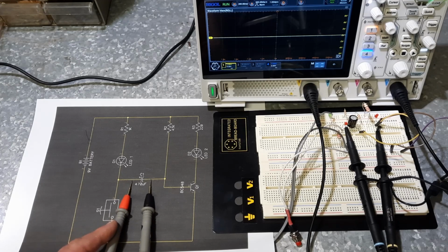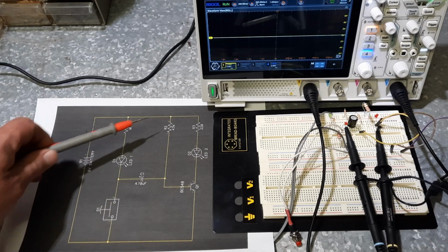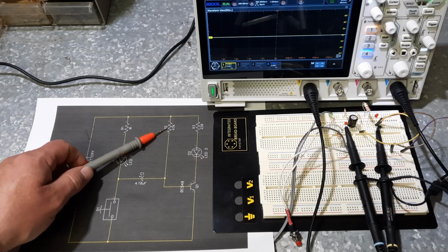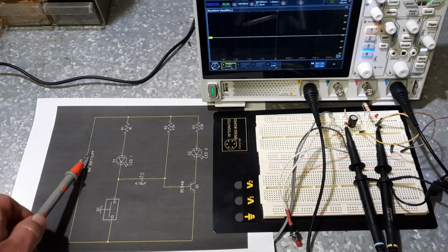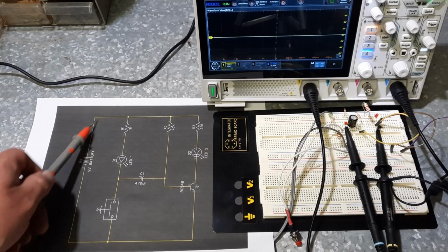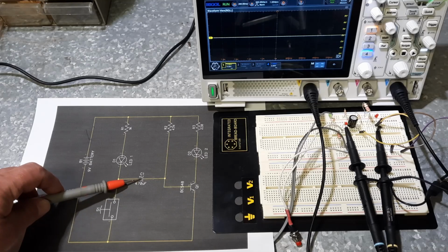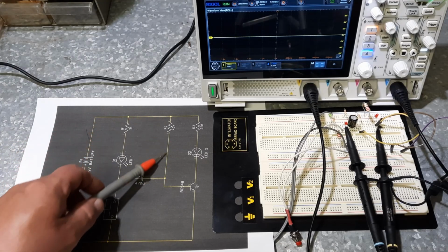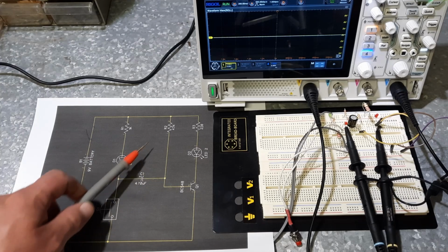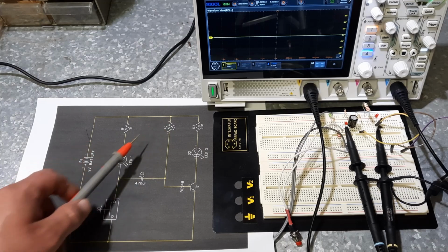It'd be falling away because it's discharging, but this resistor here is slowing it down from discharging, because like I said, it's trying to come down here, through here, and then through the battery essentially, or the battery is pulling it back to it. And so this capacitor is trying to equalize, but it can't equalize fast because this resistor here is slowing it down.